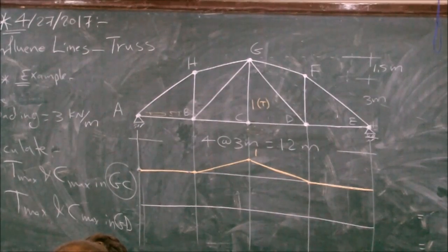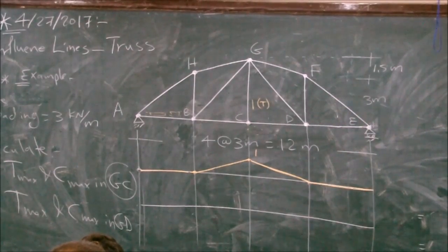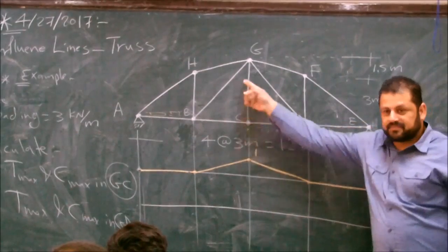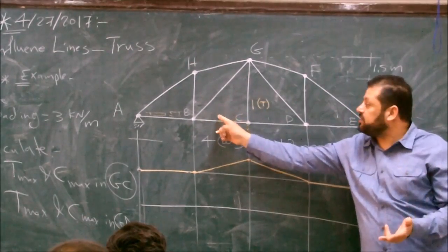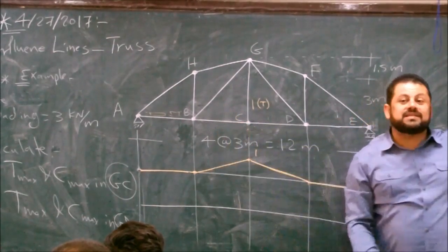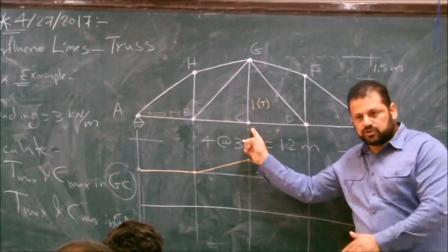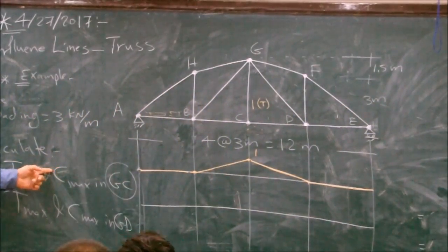The load comes from the beams only at the joints. There is load here in between, on the slab, not on the truss. The load comes. Now if you have a load in here, this will have a reaction, this will have a reaction. So you have a force in this member. This is the case here. You can't have loading on the truss directly. This loading is on the slab, transferred to the beams. Then the beams are transferring the load to the joints. Good?